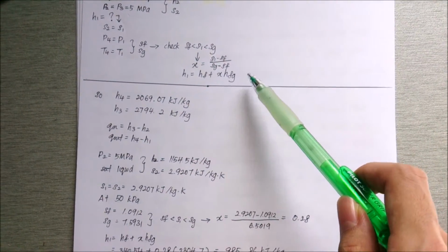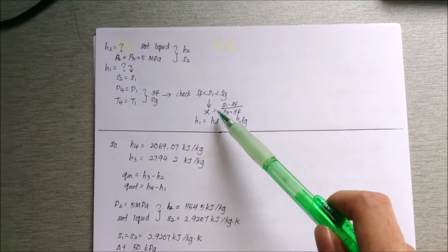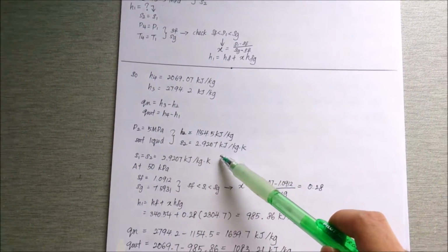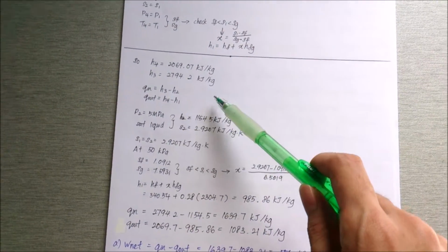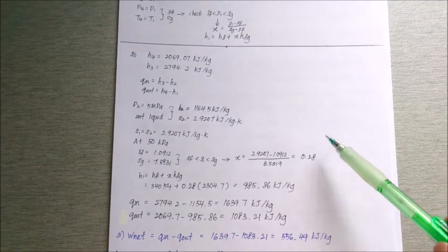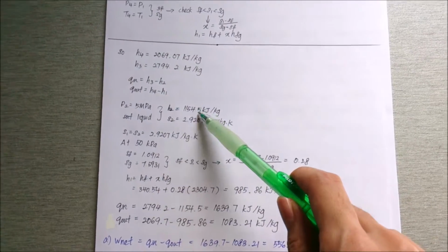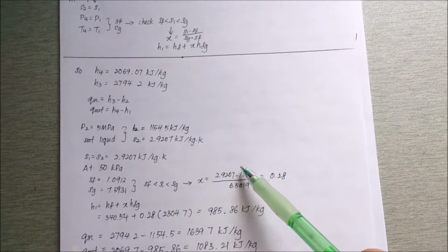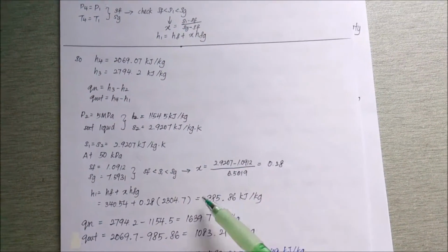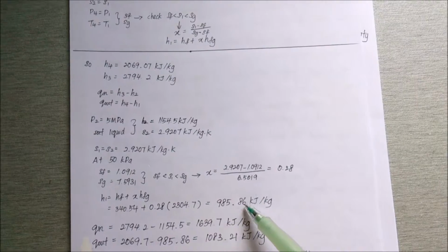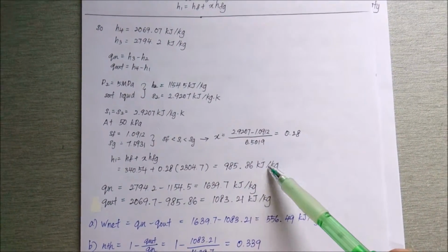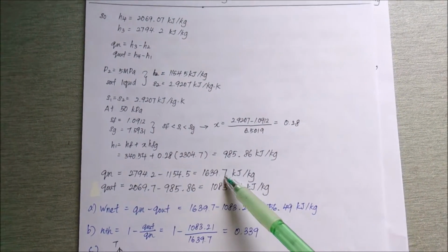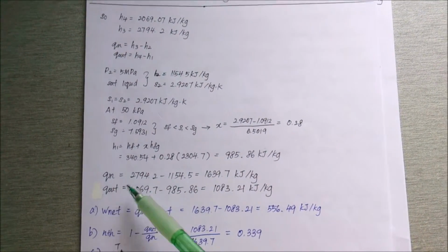So to solve the problem, we get the values of h4 and h3, and Q in equals h3 minus h2, and Q out equals h4 minus h1. We find that enthalpy 2 equals 1154.5 kJ per kilogram, and for enthalpy 1, we find the quality is 0.28, and applying the formula, enthalpy 1 will equal 985.86 kJ per kilogram. And Q in, h3 minus h2, equals 1639.7 kJ per kilogram, and Q out will